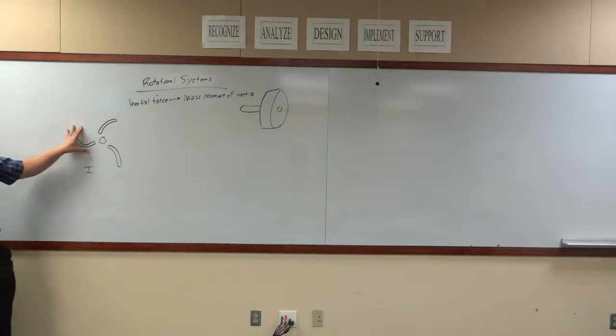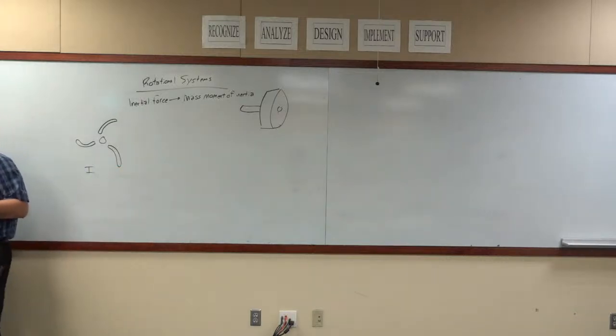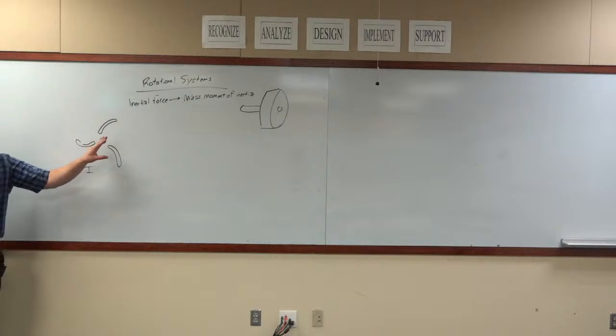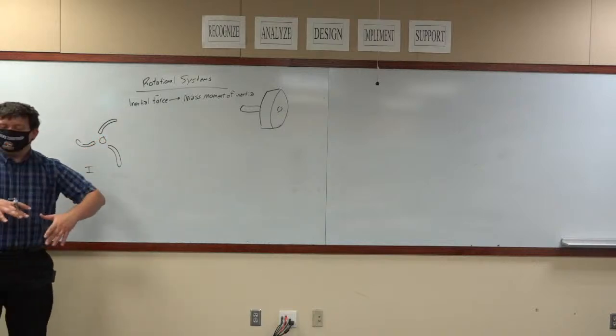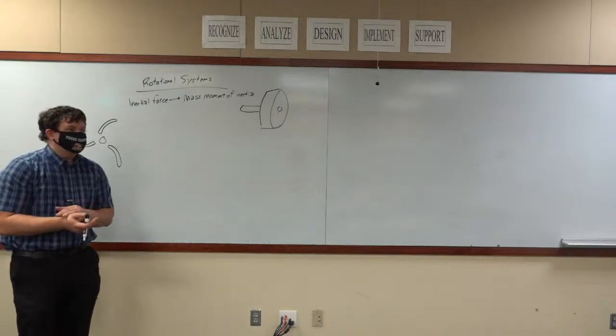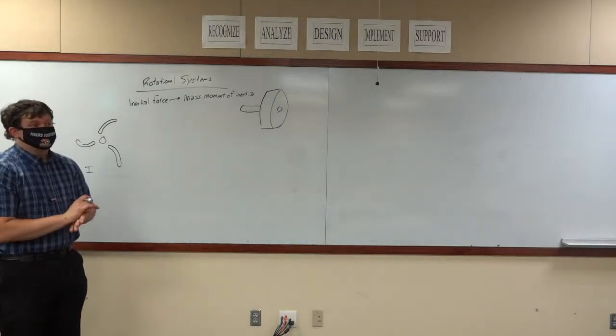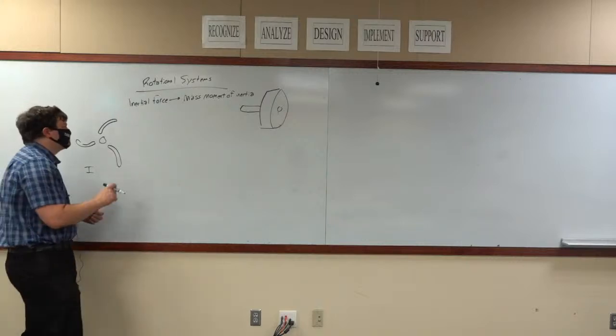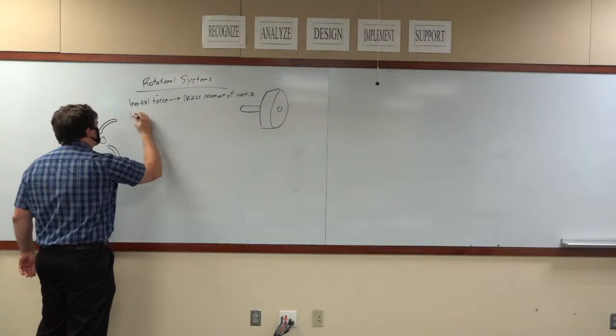So the inertial force generated by this, unlike the last one, which is pretty much fixed at m times x double dot, can change. You have the ability to adjust this in a system. Now, it would require some kind of an actuator to hold it at a certain place or bring it in. But you have the ability now to adjust the inertial force, which is kind of cool. It gives you an extra design element. Not a lot of people do this because it makes the math gross, but it is really sweet, the implications of this. You also have a resistive or dissipative force.